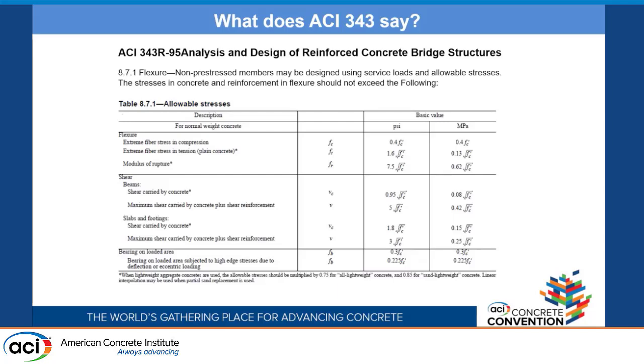So ACI 343, which I'm the current chair of that committee, this is our guidance document, analysis and design of reinforced concrete bridge structures. So these are the limits for different cases for flexure, for shear, of our allowable stresses, right? And this is for reinforced concrete.